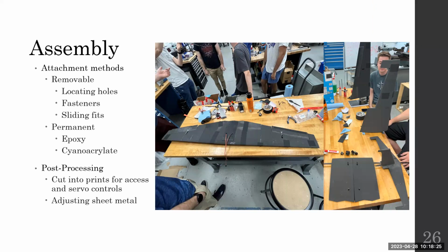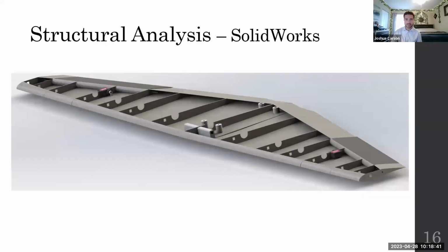Okay, just two conceptual questions about the actual wing design. Where did you locate your spar in the wing? That was at the quarter chord. Okay, cool. I'll pull that up and highlight it. That's obviously for the maximum lift location. Okay, the reason I'm asking is just because the group last year didn't know that.